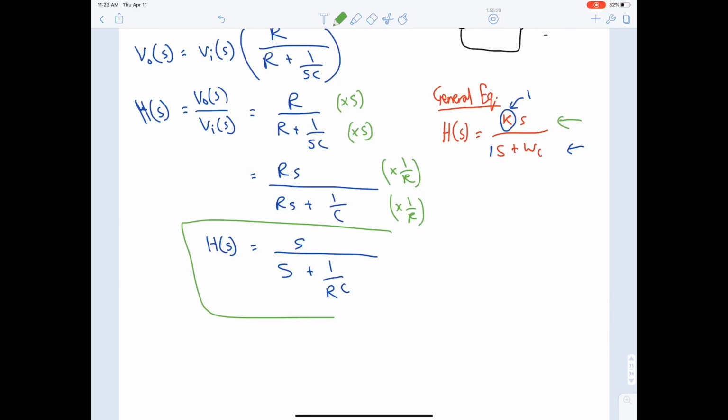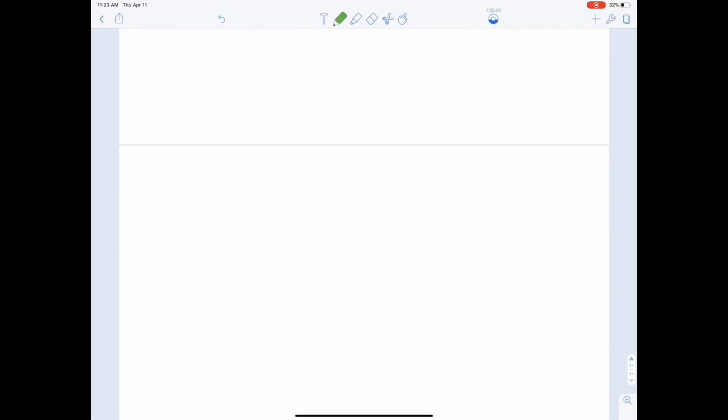because, and it's correct actually, because here we have an s in the numerator, denominator s, and this is the k 1, and all of this is what? It's omega c. Okay, so far so good. Let's now find the magnitude. Magnitude is found from its parent, which is the transfer function.